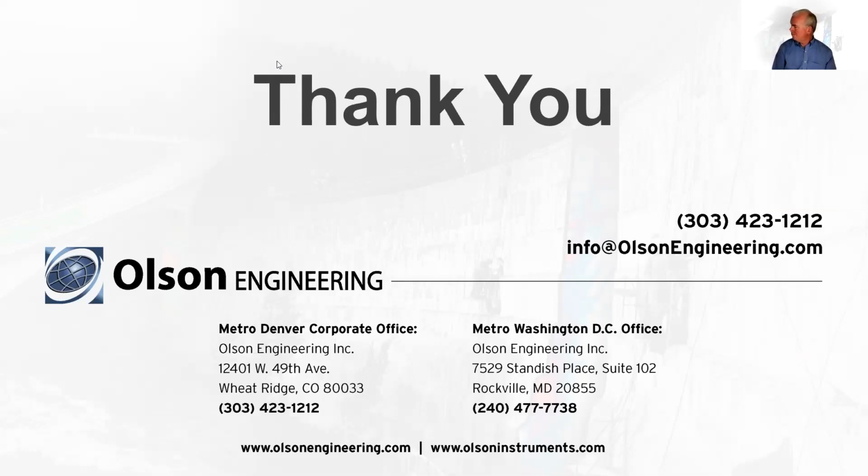So there's a couple of questions on using GPR to detect reinforcement diameter. If you don't mind, I'll just answer that one saying that you can't really do that with commercially available GPR. There are 10, 20 papers out there that show proof of concept that it can be done with much higher frequencies, typically in the 3 to 7 gigahertz range, but most commercial GPRs top out below 3 gigahertz.